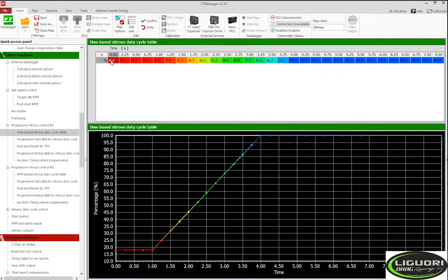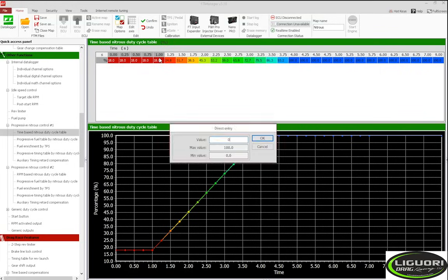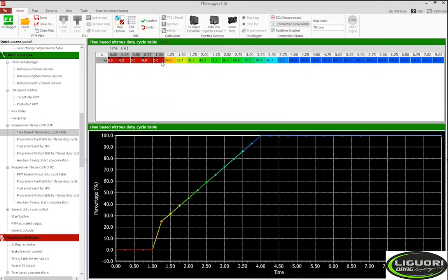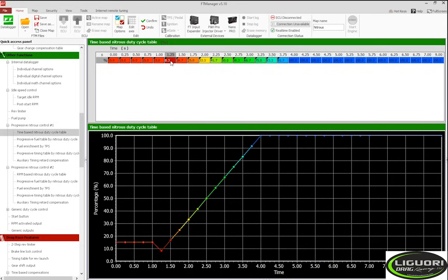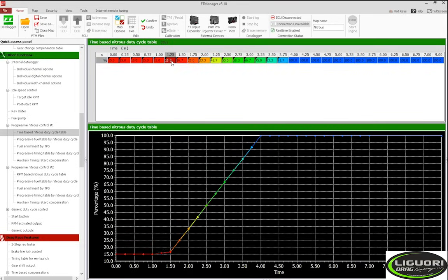And then you can adjust your values for the solenoid ramp here. So if you wanted to leave on motor, put that at 0, and you wanted to start at 1 second and ramp to 4 seconds, highlight those, click H, and it snaps the table down. If you wanted to start at 15%, and then you wanted to gradually go up, you can just click these and adjust with the up arrow, or the plus button, sorry.